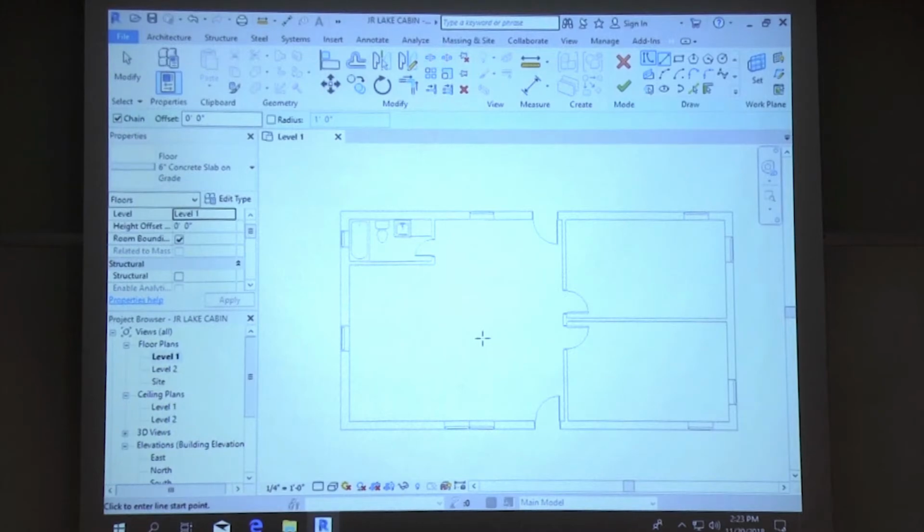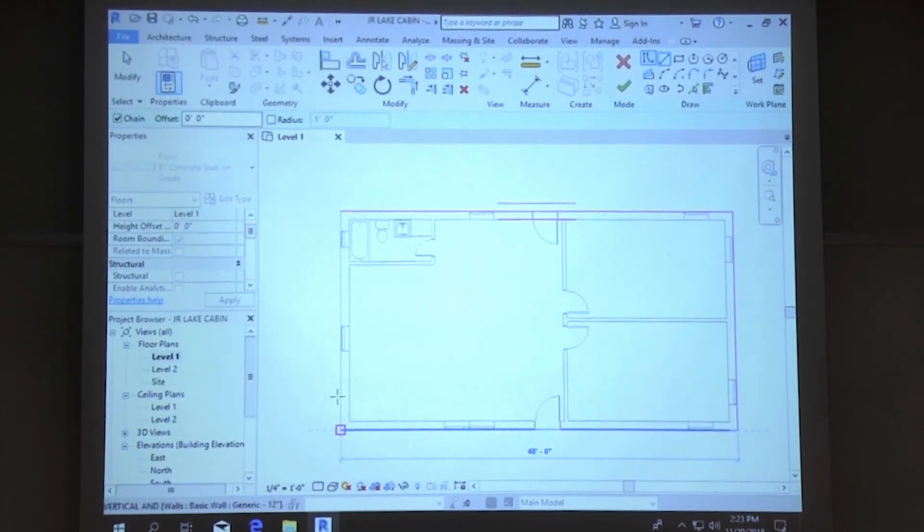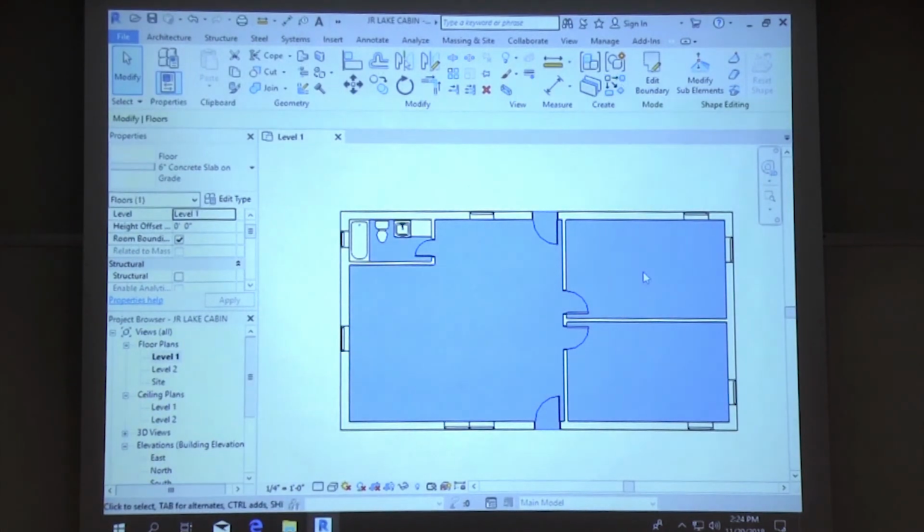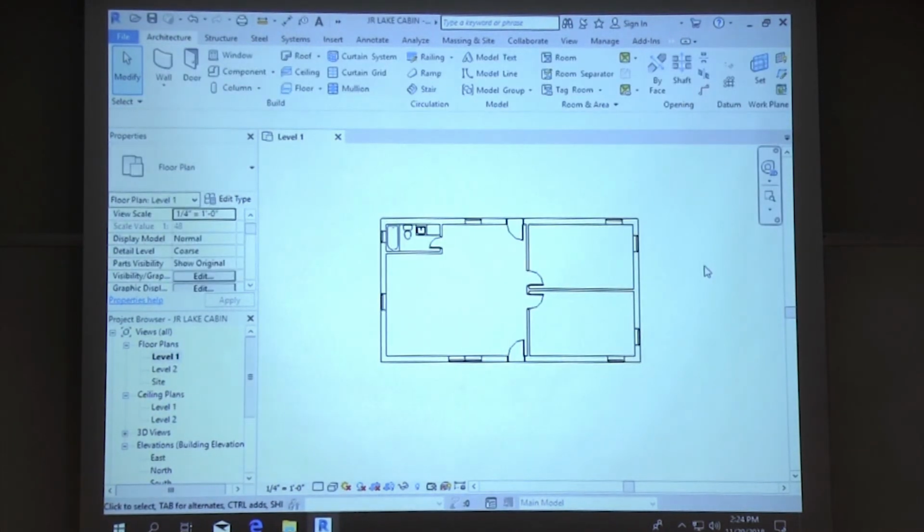All right, we're back to drawing. Back to where we're supposed to be. And then you're just gonna click. Click. You're gonna trace what has to have a floor. Cancel twice. Escape twice or cancel twice or click on the modify button, whichever, just to escape the command. Once you see your footprint completely traced with this pink line, hit the green check. There you go.